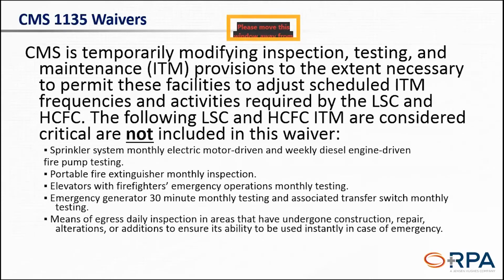So what does this do? Well, they're temporarily modifying the ITM provisions, and I have the specific publication if we want to go into the fine granular detail. But I wanted to focus more on what they did not include in the waiver. So there's a lot of allowances for ITM, so you need to relax some of your testing and maintenance for different services and protection features, and that's all well and good. But they specifically called out these items that were not included in that, so we have to continue to maintain those items as listed here.